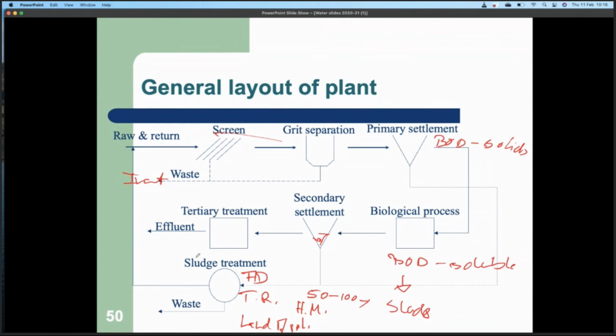And the other big thing is that these heavy metals are not just maybe the ones that we are worried about, I don't know, mercury and chromium and stuff, but you also have an awful lot of iron in there. So if you're talking about ion exchanges and resins and heavy metal traps and all this sort of stuff, a lot of this will be taken up with iron. So it's actually very hard to remove the metals that you really are concerned about, that give you the toxicity, versus maybe iron or maybe even a bit of copper in there and that sort of stuff. All that stuff will conflict your process.